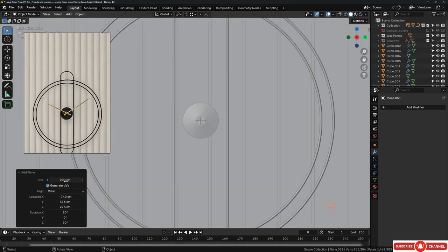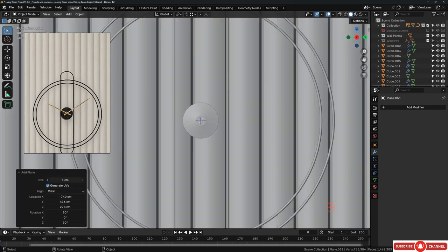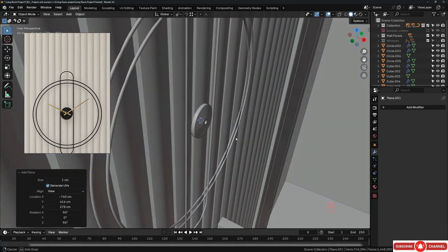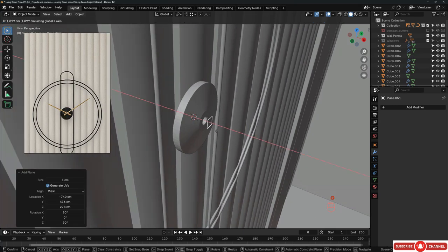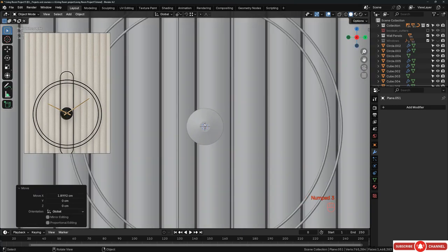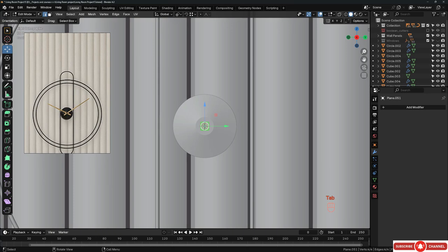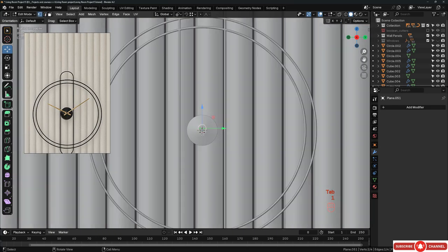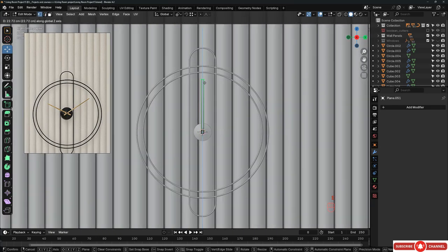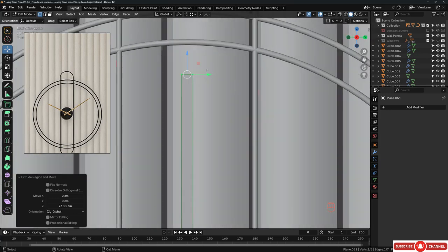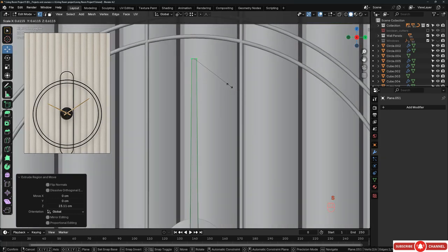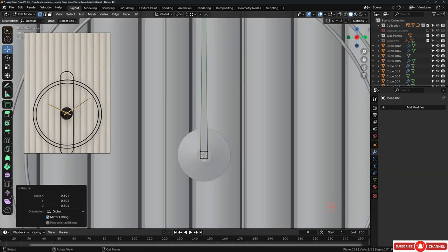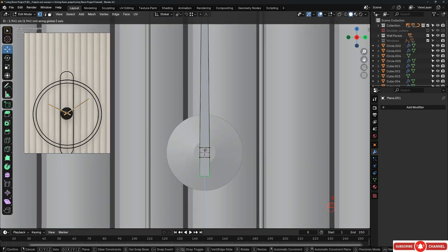It is very big, as you can see, it's 200 centimeters. Let's change this to 1 centimeter, make it very small, and I just want to take it out like that. All right, and let's tab to go to the edit mode, and I will select these vertices and hit E to extrude those almost right here. And you can scale it just a little bit, make it thinner. And from this side, you can extrude it just a little bit like that.